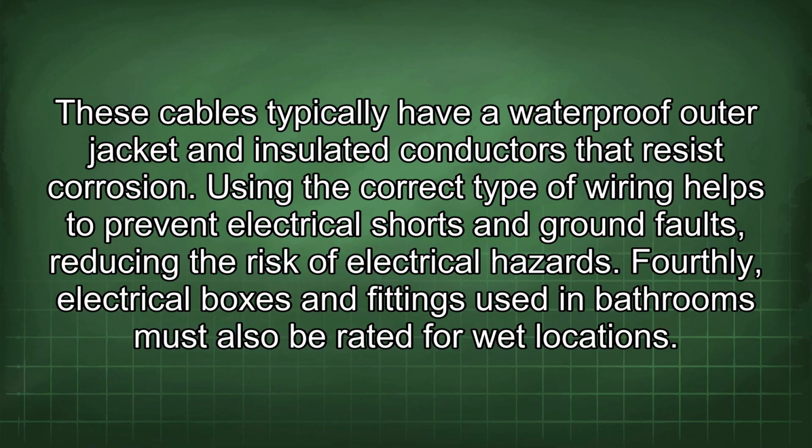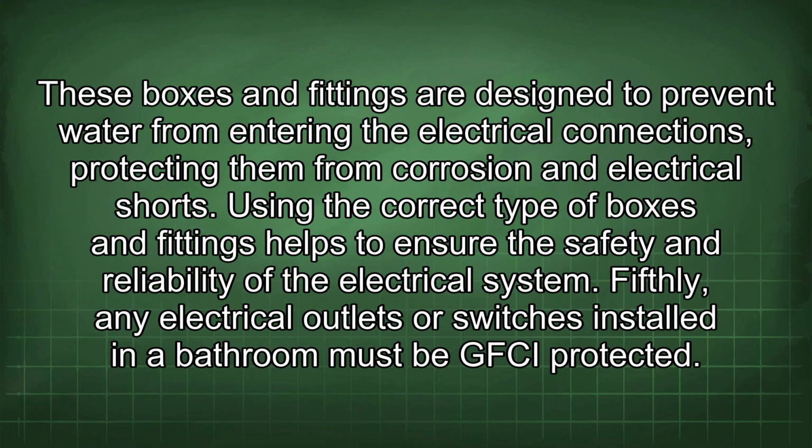Fourthly, electrical boxes and fittings used in bathrooms must also be rated for wet locations. These boxes and fittings are designed to prevent water from entering the electrical connections, protecting them from corrosion and electrical shorts. Using the correct type of boxes and fittings helps to ensure the safety and reliability of the electrical system.